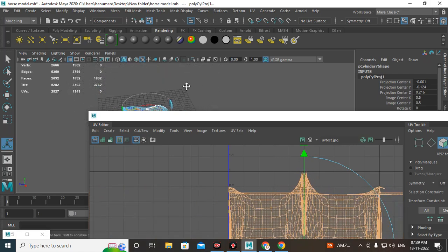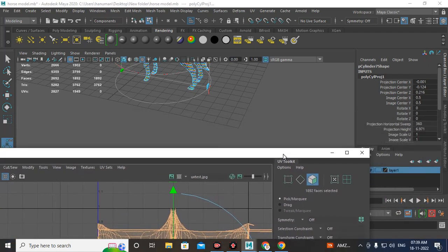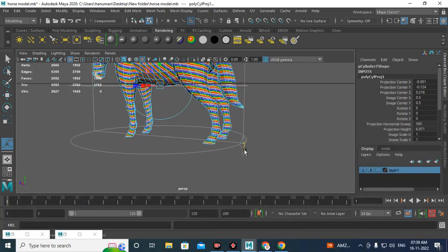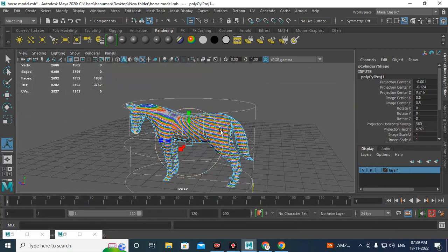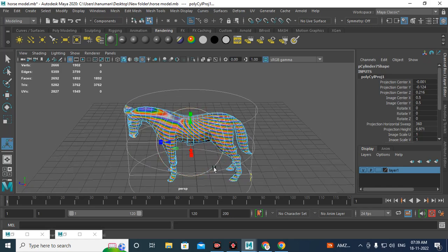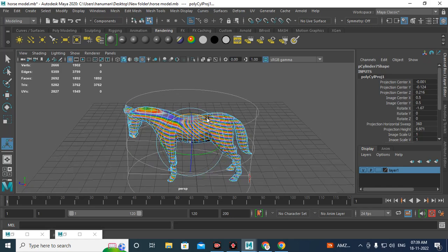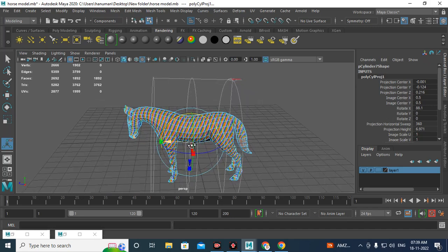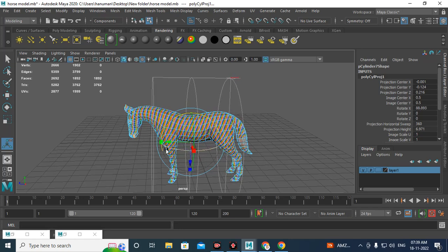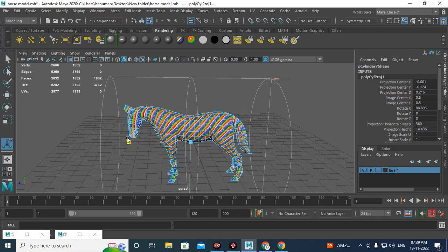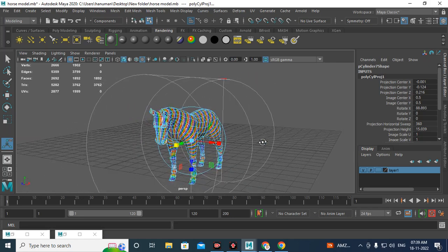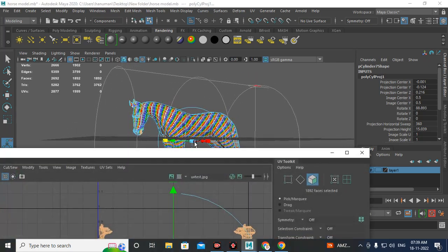But if you want to get a horizontal manner, just click on this transform tool down. Rotate it. Then it opens the move tool, scale tool and rotation tool at the center. Click on the rotation tool circle and rotate like this. Okay. Then scale this to stretch it up to the body start and end.